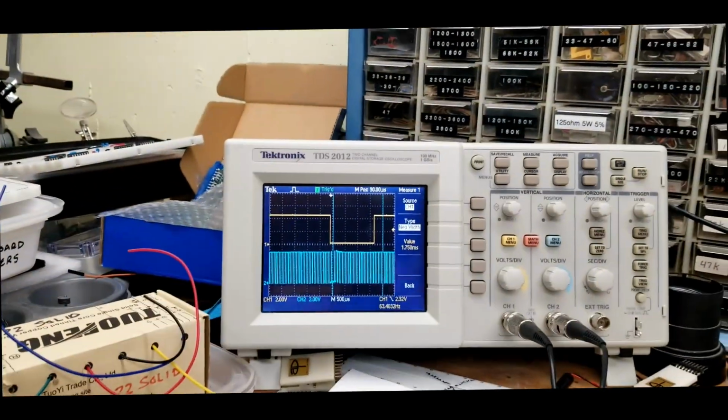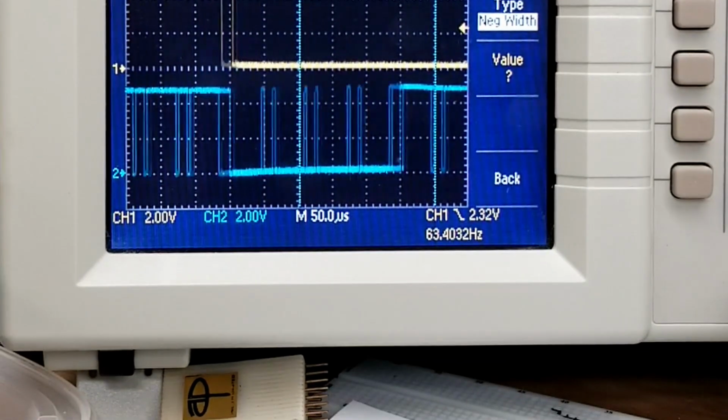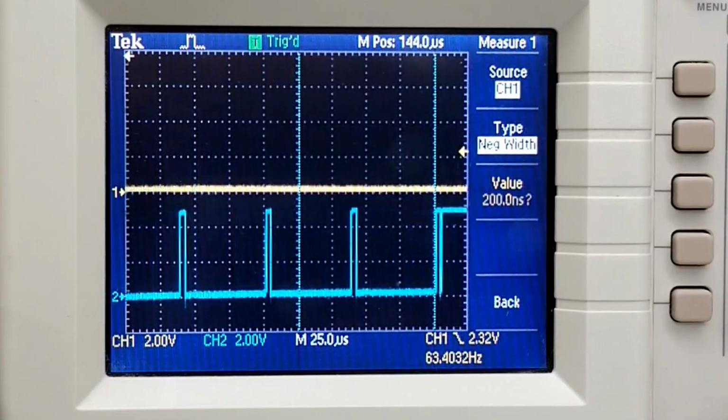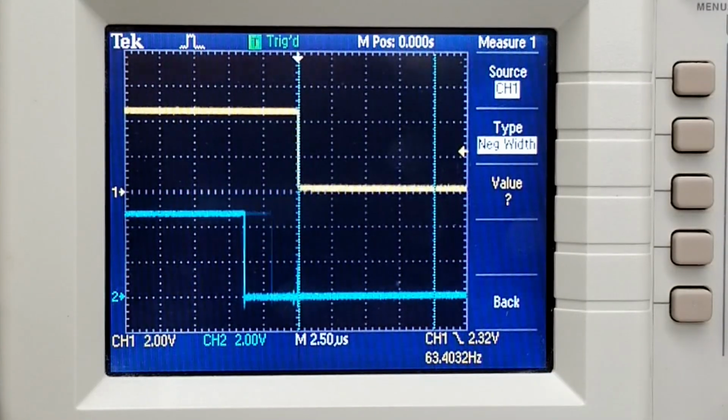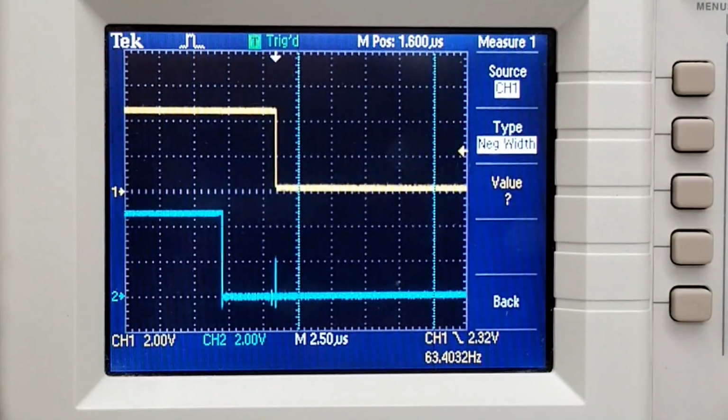Let's look at the composite sync on the scope. We'll trigger on the fall of V-sync. Exactly what we expect. Inverted for 4 horizontal steps. And some switching noise from lines and gates not perfectly timed.